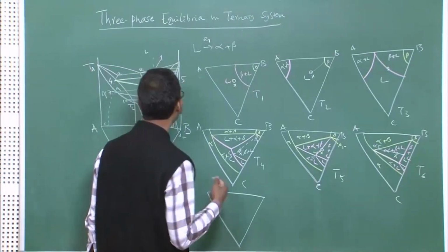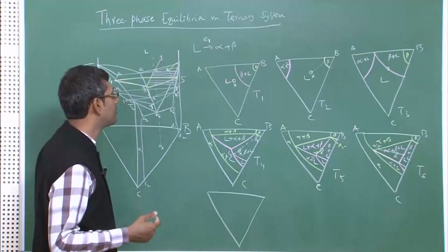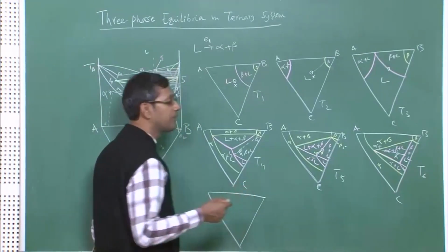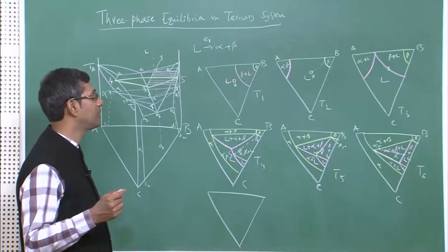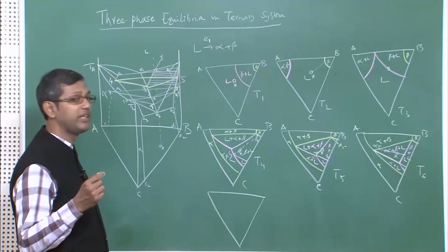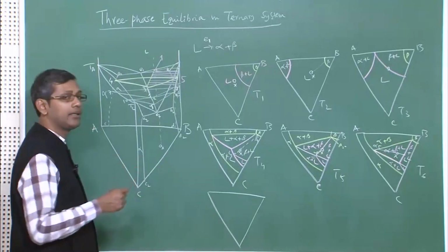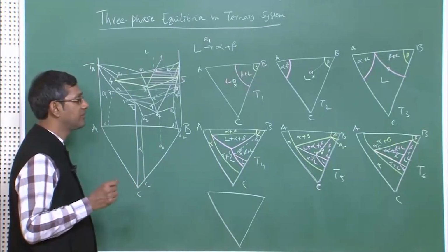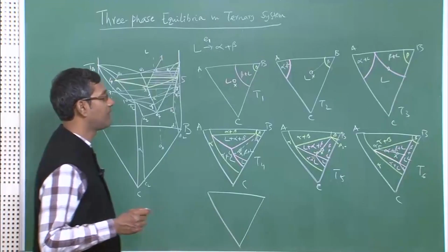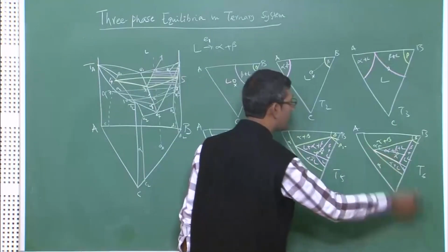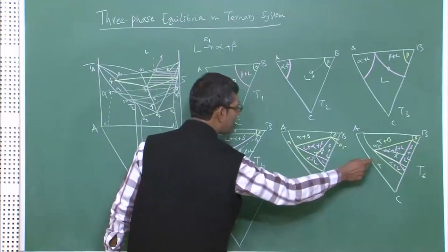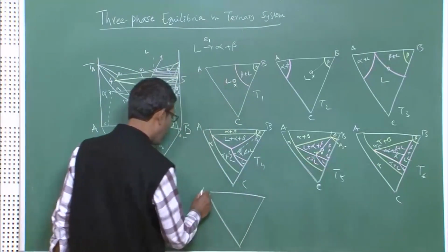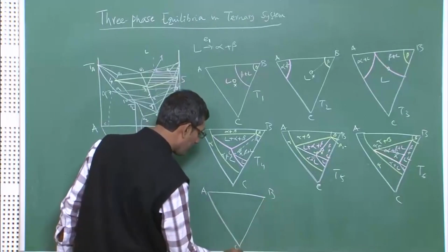So, as compared to the binary phase diagrams, where the eutectic reaction or the three phase equilibrium takes place at a fixed temperature, it is basically a non-variant reaction. Here you have a monovariant equilibrium. Because of that, this eutectic reaction can take place over a larger temperature range, and that is what you see here. Although it started forming here, it will also keep forming at lower temperature.